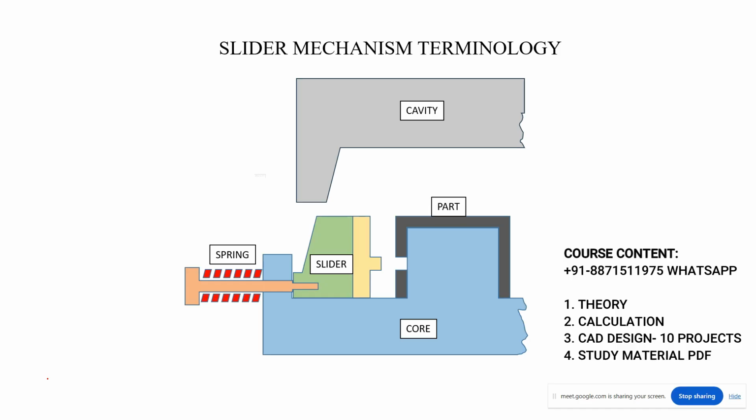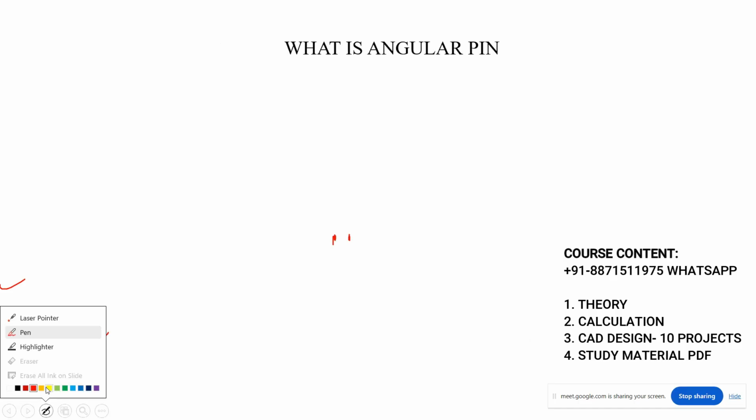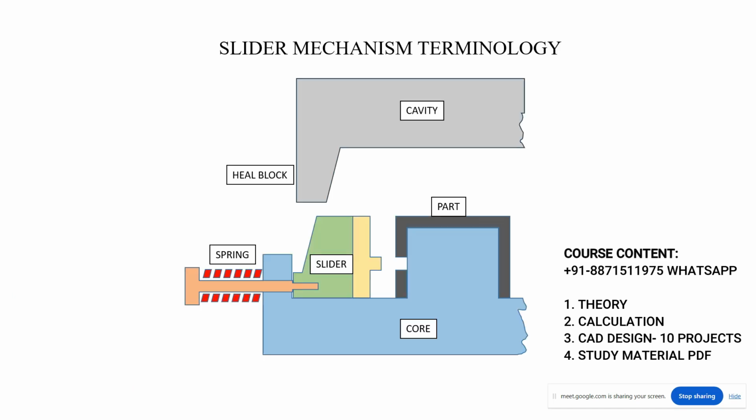See here, this is the component we have here. You can see that this is nothing but the heel block portion. Okay, now see here, one minute. Sir? Yes. Again, for the ejection of the part, you have to use a sleeve. Yeah, sleeve is nothing but a type of ejection system, like pin ejection. For example, pin. What is the working of pin ejection? Pin is directly forcing the component, right? But the sleeve is for the edge of the component, right? By the sleeve, the component edge will be contacted, right?